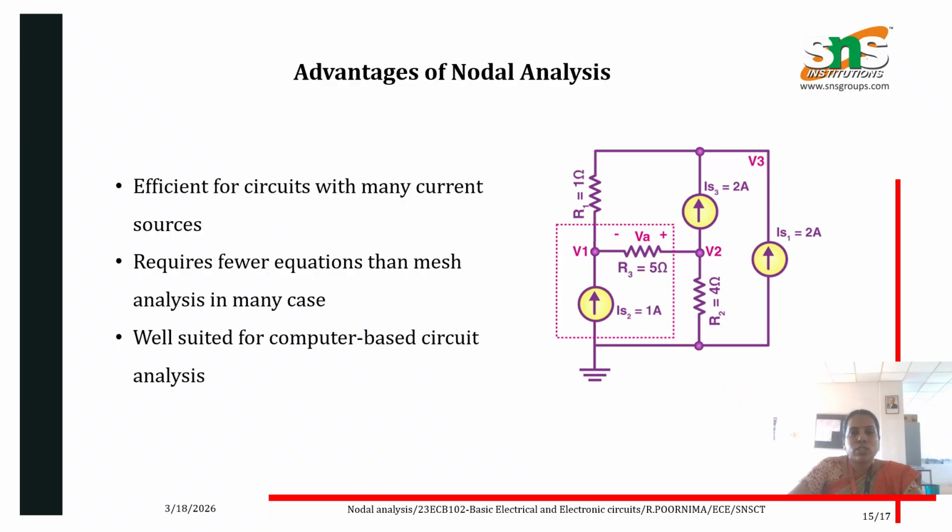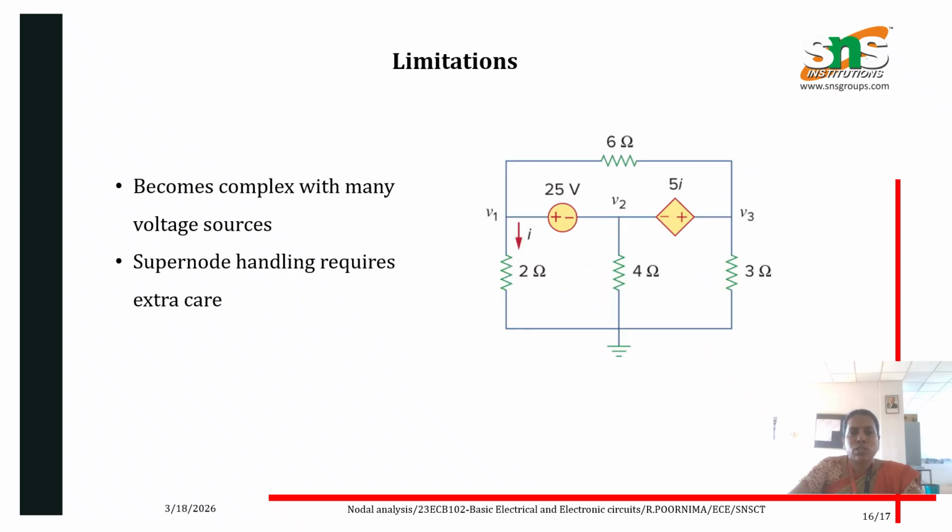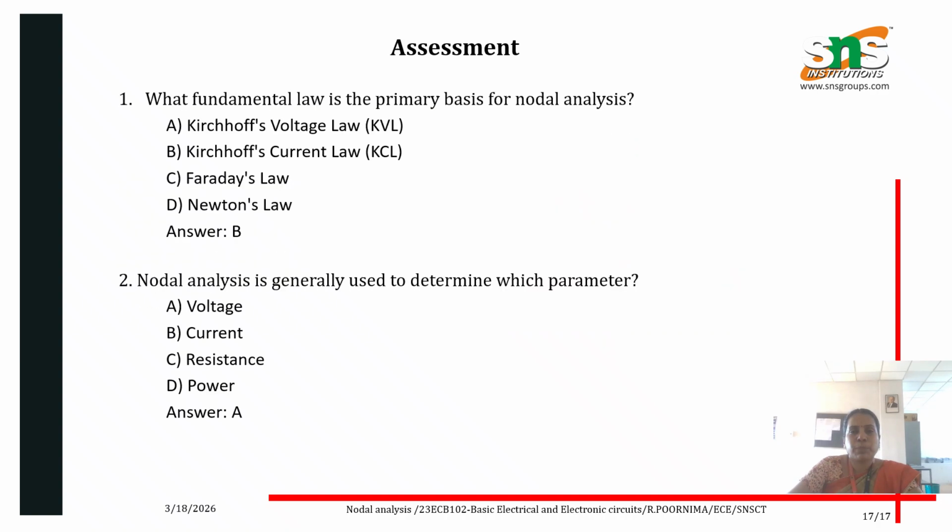Advantages of nodal analysis: this method is efficient for circuits with many current sources, and requires fewer equations than mesh analysis in many cases. It is well suited for computer-based circuit analysis. Limitations of nodal analysis: it becomes complex with many voltage sources, and supernode handling requires extra care.